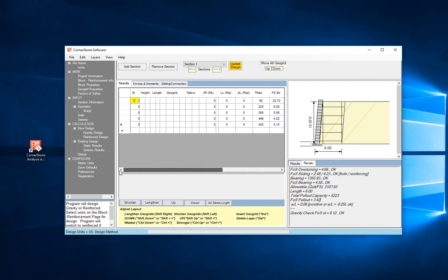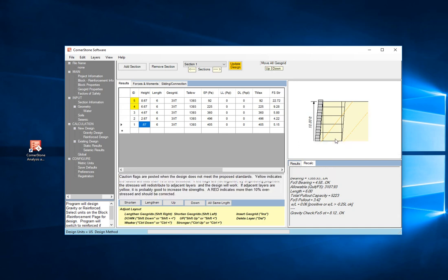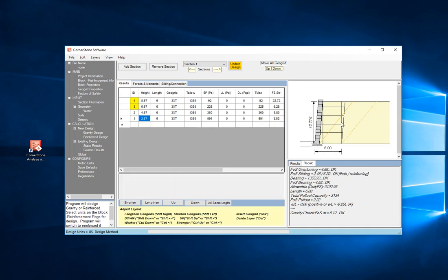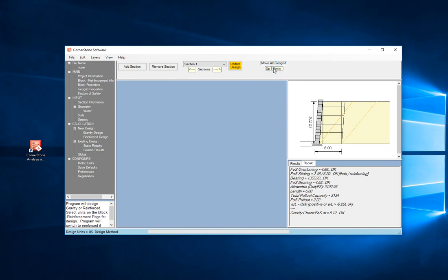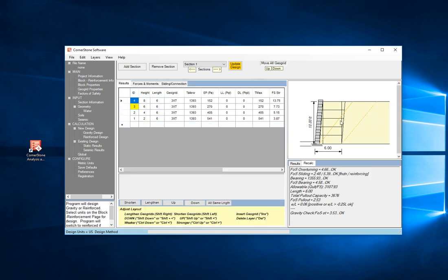Just a quick note on this page. We're up here. You want to get rid of that bottom grid. What we can do is hit the delete button. It will delete the bottom layer. It will update the calculations. I've got 4 spaces, which is too much, so I can move the grids down. Update the calculations. This will pass. Maximum 2 block spacing, 2 times 2 foot spacing, 2 times the depth of the block. 3 down from the top, 3 up from the bottom.